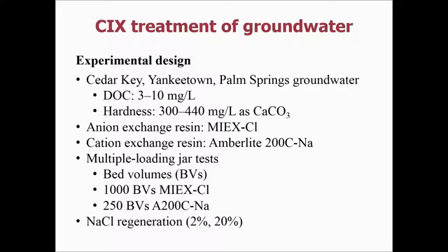We continued to use the magnetic anion exchange resin because from previous work we've done, that's a very effective resin for DOC removal, although there are other non-magnetic resins out there that are useful and can remove DOC well. And then we went with an off-the-shelf standard cation exchange resin, and we did that again because we were looking for a higher capacity resin for the hardness removal.